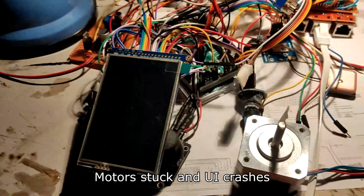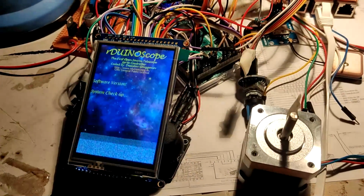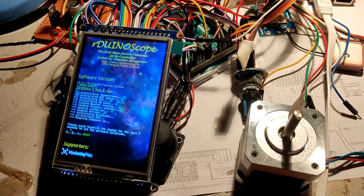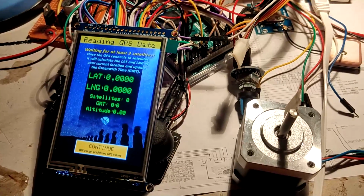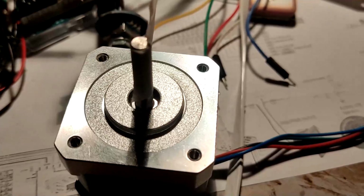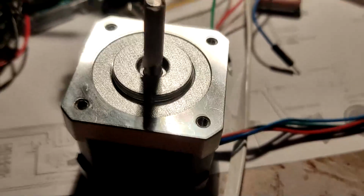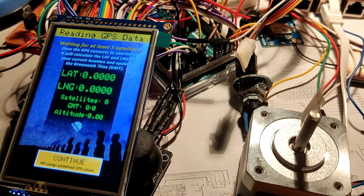Now let's take a look at the troubleshooting and how to solve the issues. The first problem was the motors were stuck in place. They wouldn't spin at all, making a high-pitched noise, and that finished by crashing the UI. To solve this issue, you must supply the motors from the 12 volts input directly from the battery instead of using the 9 volts output from the voltage regulator. I also had a sticking issue of the screen, but it was because of the memory card. I replaced it with a quality one and there was no problem anymore.